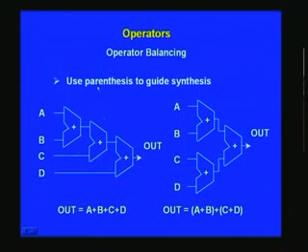And we have one more thing before we wind up. Let us say we want to have an arithmetic operation done. Let us say a plus b plus c plus d is what we want to compute, right? If you put this condition here, the synthesis tool will map it like this. It will put 3 adders. A plus b result will be available here. Then this will in turn be added with c, and that will appear here and get added in the final last adder, and finally the output will be this, right?